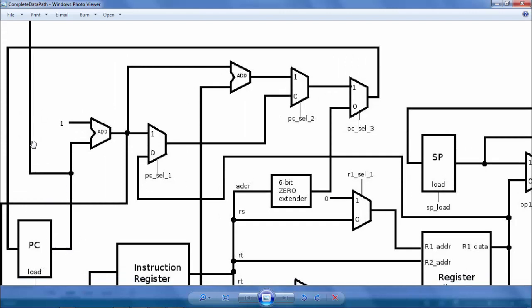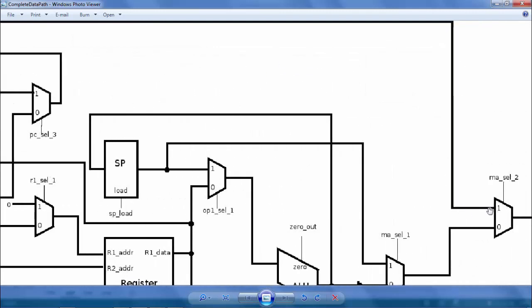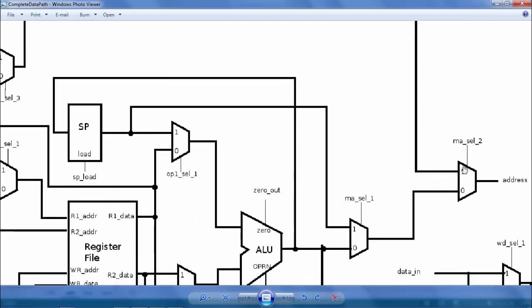This program counter is driving that address into terminal 1 of the multiplexer. So that means my MA selection address 2 must be 1 at that point, whereas for memory address selection 1, it really does not matter if it is 1 or 0. It's a don't care, right? But for our example of control signal generation, we need to come to a definite Boolean value. We cannot just put an X there.